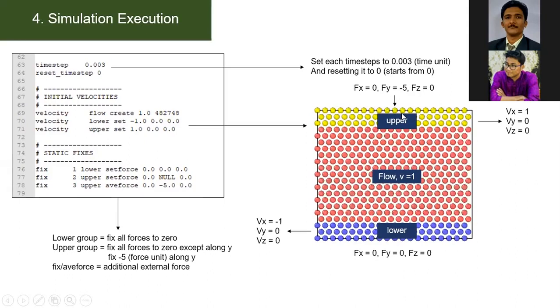So you can also calculate the pressure from here, right? As we are applying force over the area, that is pressure, so we all know that. So you can calculate the pressure on the top layer and provide this value. And again, this value is in Lennard-Jones units, and if you're using real units, then you have to provide according to those pressure units. Okay. So this is actually providing an external pressure on the upper layer.